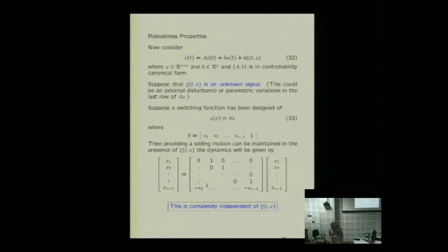Okay? So the equivalent control typically, if you take the A and B and you apply the equivalent control in terms of an analysis, you will find the poles you picked for the sliding surface and M zeros for a problem with M control inputs. And that reflects the reduced order nature of the problem. But the poles are there, they're embedded in the dynamics you picked. It becomes more difficult if you use a nonlinear sliding surface, because of course we don't have the same notions of stability. We have to use different notions. But for a linear system, the poles are just there, just as for the hot air balloon, the -1 plus or minus j would be the poles of that free second order system, which was the dynamics. The difference is it isn't the control that's giving you that dynamics. It's the choice of S that's giving you that dynamics.